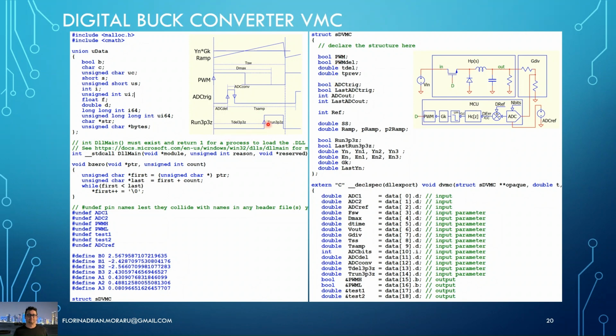digital regulator. Yeah, so we can play with this ADC del. We move the moment when we are sampling the output voltage, and then here we can also play with the moment when we initiate the calculation of the digital regulator and how much time it takes to calculate the linear difference equation. In principle, we need to have the new value available before starting a new switching period. In the code, I will update this on the rising edge of the PWM signal.